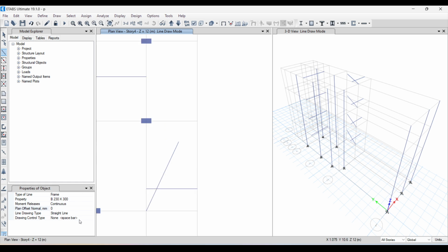Now there is one another very interesting option. Is fixed length and angle. Now suppose your beam is 2000 millimeter and the angle is 45 degree. Now from this point suppose it is at an angle of 45 degree and 2000 length, then just click. Now click anywhere, it will be 45 degree and this length is 2000.